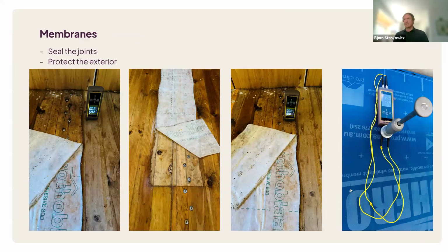We can also use these to protect floor joints. Now, why am I showing this? This was a building that's been monitored perfectly and looked after, but one room was forgotten. For some reason, it was a bathroom somewhere in the inside of the building. But we had membranes just glued over the lap joints. And you can see how just a couple of boards beside it, the moisture content sits at 26%. And below it, there's some migration and water gets to the joints. So it obviously rises, but it doesn't get to a point where your alarm bells go up in a way that you say, okay, we're having a huge problem here. It's sitting at 18%. That is borderline. We don't want to really go further than that, but we don't get to a point with CLT in this particular location where we have troubles.